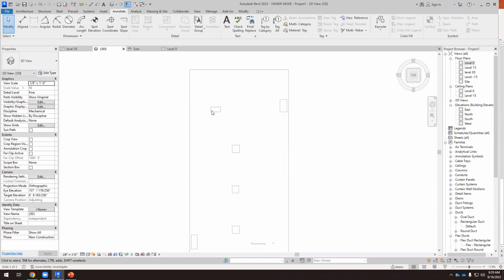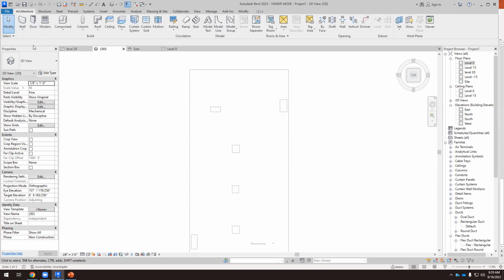The air handling unit is going to be close to this one. So this is the first thing we're going to do. By the way, make sure that we're working in a mechanical discipline. Discipline should be mechanical. You notice that because we can select the walls. If you change to architectural discipline, then you will be able to select the building, but we don't want it.